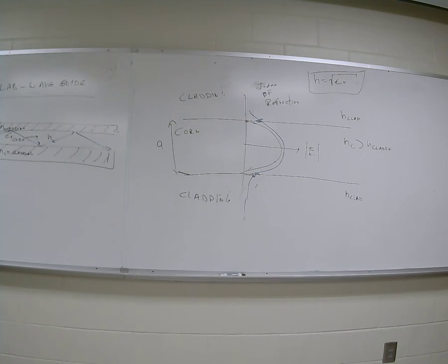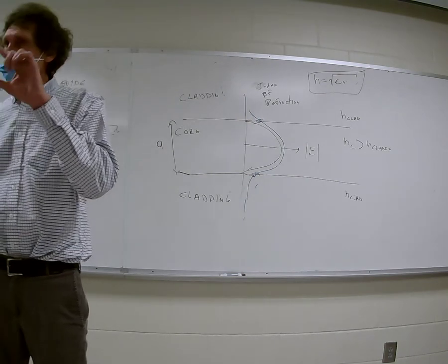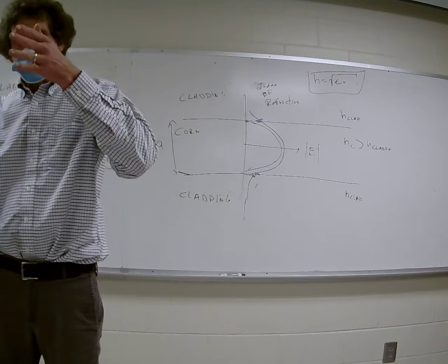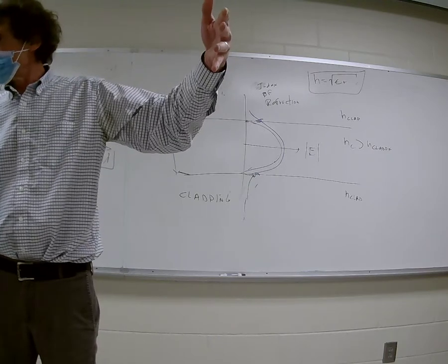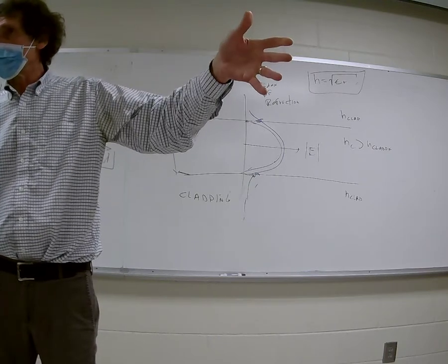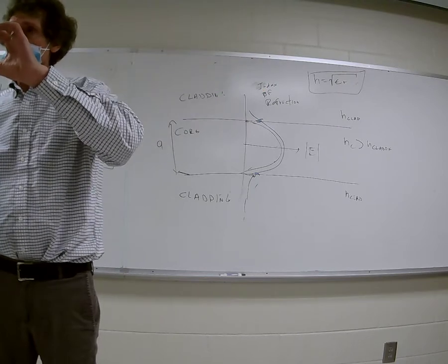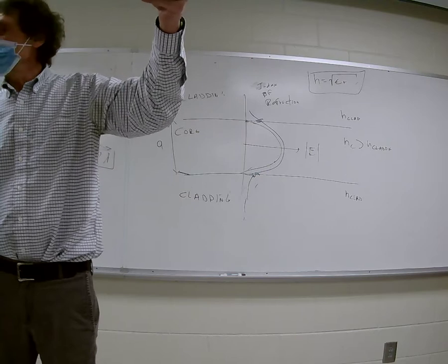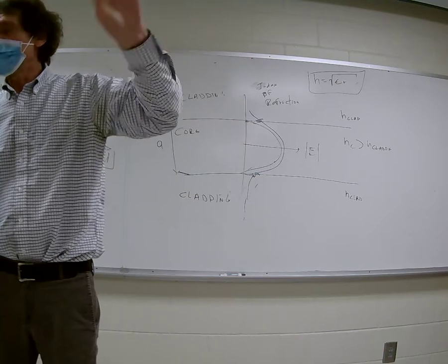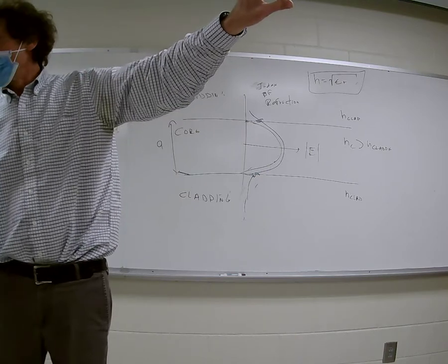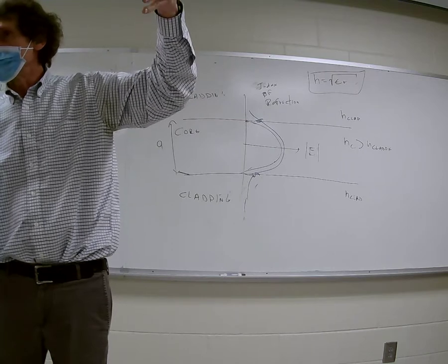Now, I'll try to explain this in the simplest possible way. When you have a capacitor and you charge it up, there's electromagnetic energy around the capacitor, but it's not propagating, correct, class? It's just a static field, right? If you charge up a capacitor, you got a voltage difference. If we had an E-field meter, we could measure an E-field here, but that thing isn't launched. All right? This is called an evanescent field.